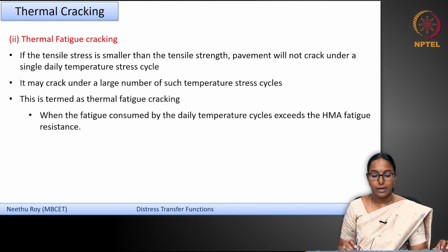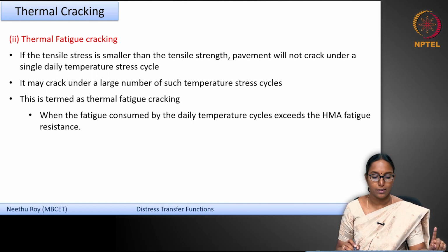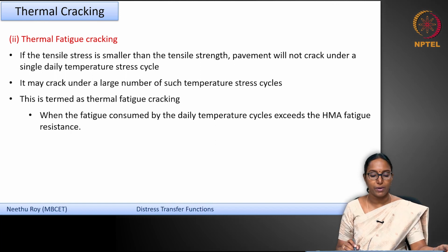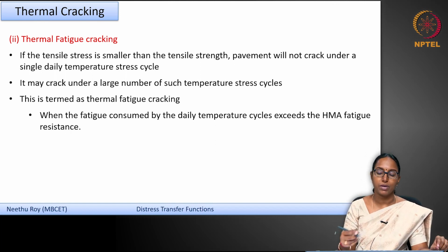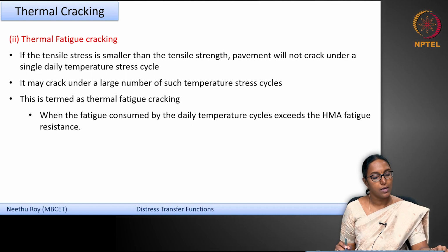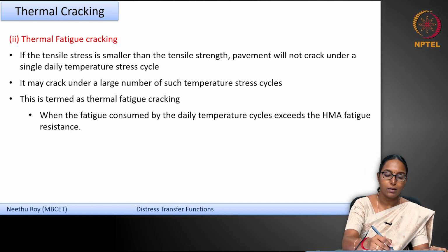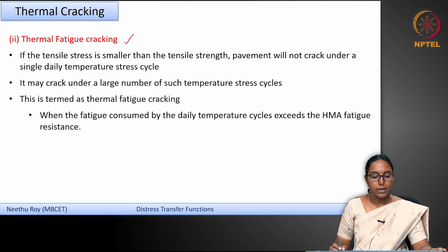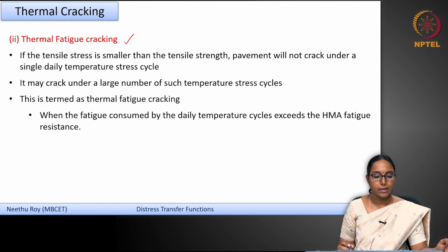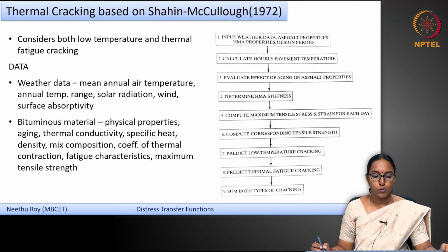The pavement will not crack under a single daily application of this thermal stress due to one temperature stress cycle, but it may crack over a period of time when a large number of such temperature stress cycles are applied on the material. This is called thermal fatigue cracking. When I say thermal cracking, it is a combination of thermal cracking plus thermal fatigue cracking. Again, there are various approaches used to consider thermal cracking in the design.